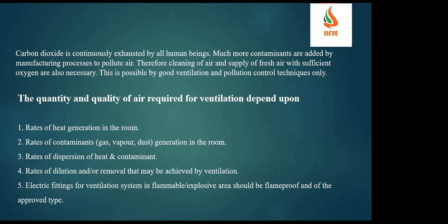Then the rate of dispersion of heat and contaminants, and also the rate of dilution or removal that may be achieved by the ventilation. Dilution means how much heat you are able to dilute or remove from the work area with your existing ventilation system. That is also one of the factors we have to see, so that we design our ventilation system accordingly.